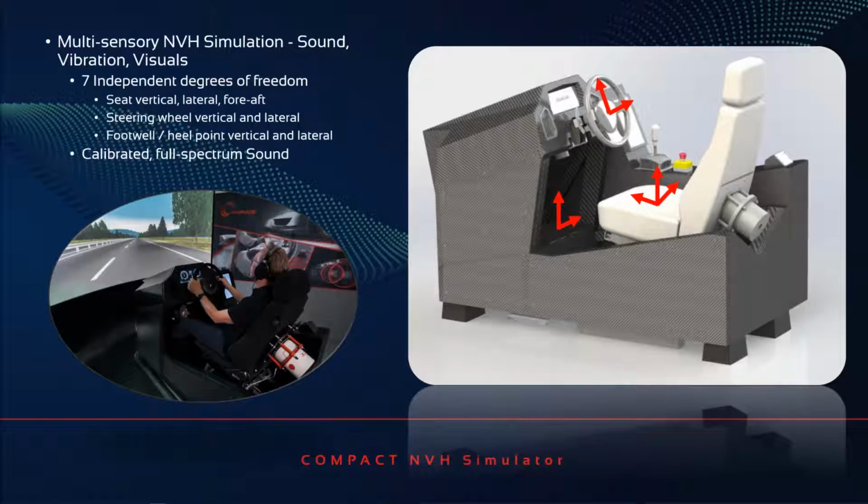Of course, the vibration is calibrated and equalized so the exact vibration stimulus which simulates the vehicle is delivered to the driver. Sound is also a critical piece of the evaluation experience, so highly accurate calibrated sound is provided through high-quality headphones and a subwoofer. It is really the combination of sound and vibration that delivers the unparalleled NVH experience.